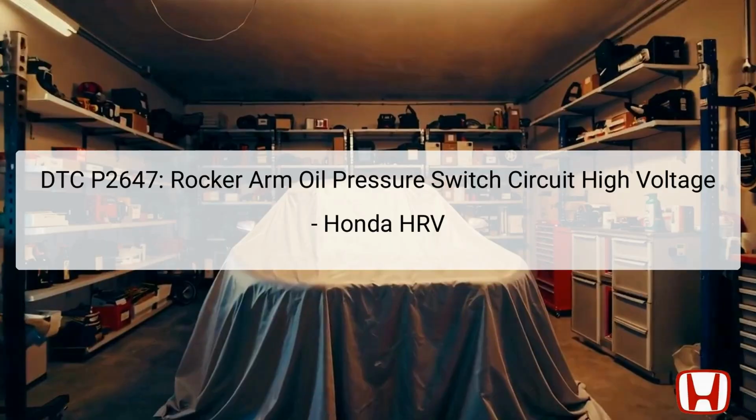The Diagnostic Trouble Code DTC P2647 indicates a high voltage condition in the rocker arm oil pressure switch circuit. This error typically relates to the variable valve timing (VVT) system, concerning how the engine operates under various conditions for optimal performance. The rocker arm oil pressure switch plays a crucial role in this function by monitoring oil pressure sent to the rocker arms, controlling the timing of the intake and exhaust valves.